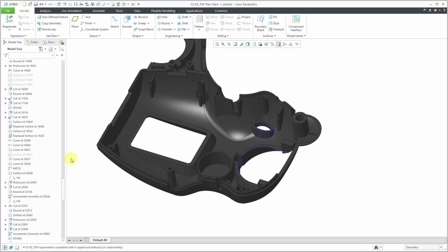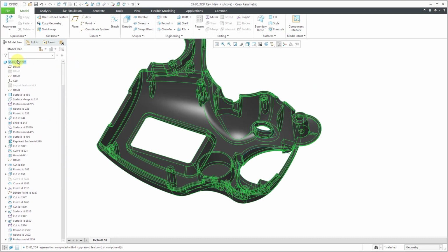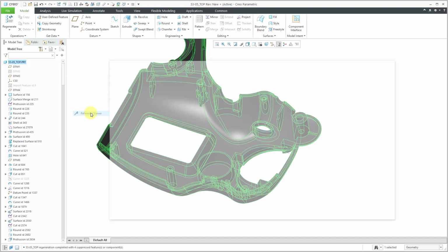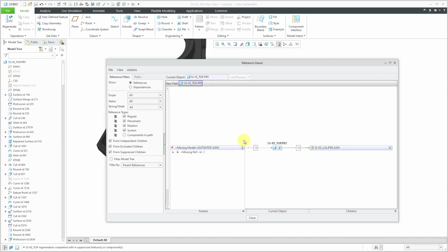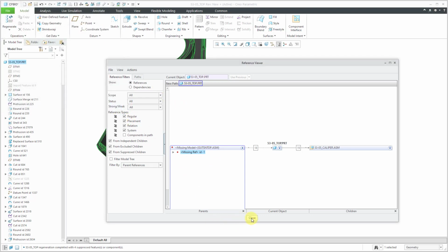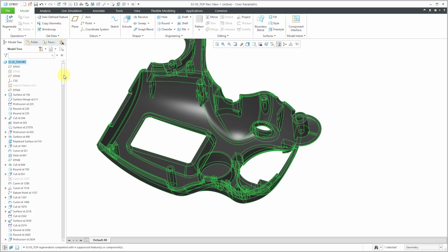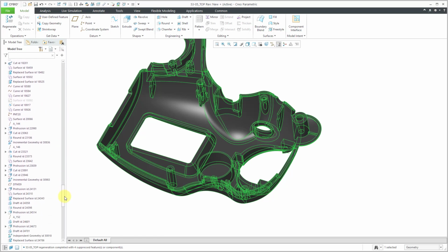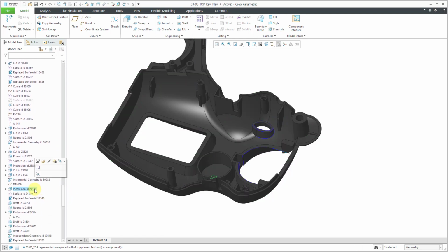And as I continue on in here with a few more of these, just want to mention that one way to prevent these problems is by using data sharing features like your copy geometry features, also using your shrink wrap features for bringing these references in, because your data sharing features have the ability to have their dependency turned off. Here we're using something called direct external references, and these are the kinds of problems that you end up with. So take a look at this one.